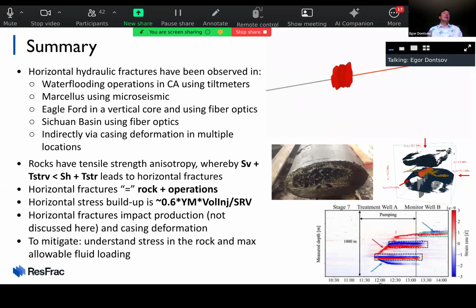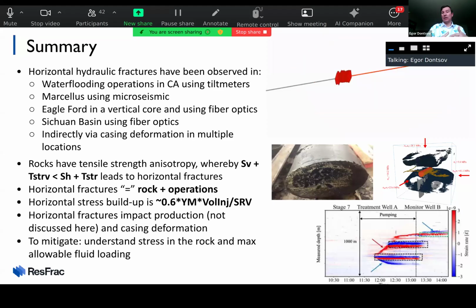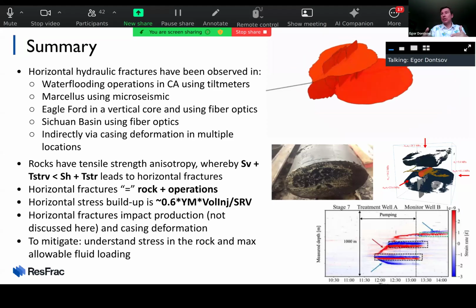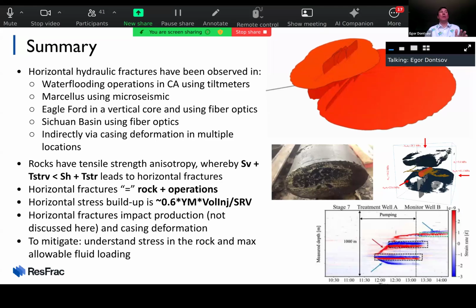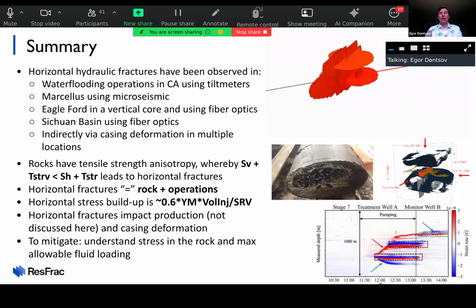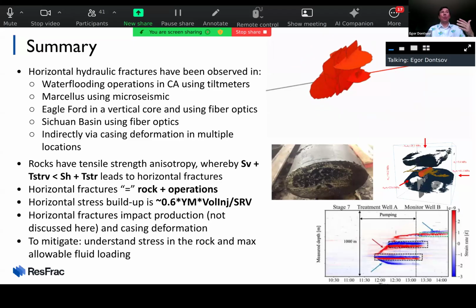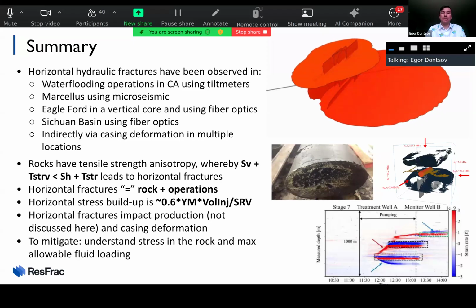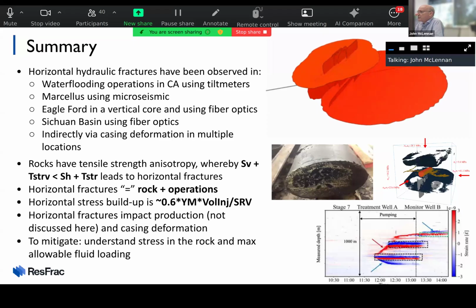But again, what happens is that once you leak off, you start having poroelastic effects, right? You increase pore pressure in the rock, and this also causes swelling and some stress shadow. It's probably going to be reduced, less than the equivalent shadow of an open fracture, but it's not going to go away completely. Long story short, I didn't consider it because I wanted the simplest estimate possible, just one simple equation which can tell us which parameters affect stress shadow.